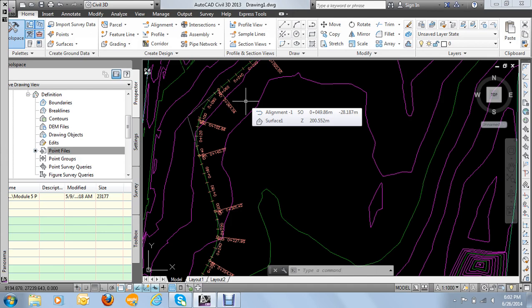Now if you had already done the surveying and you just created the alignment and then the profile, you cannot go back to site and start from the beginning, surveying from the start point up to the end point, because it's obviously costly. So what we normally do is pick the points and survey again on those critical points.